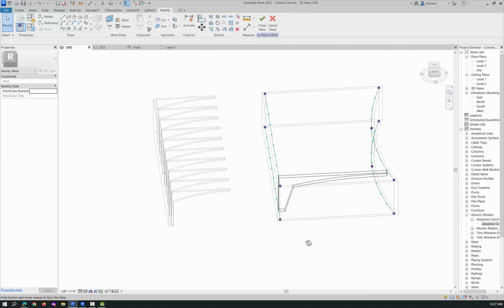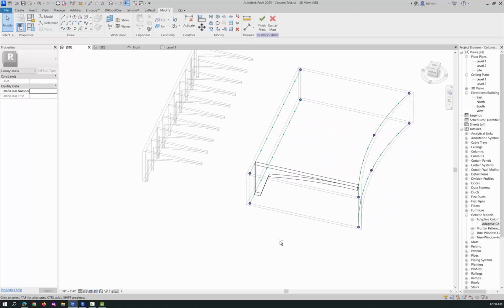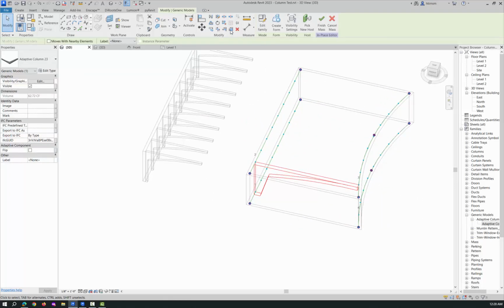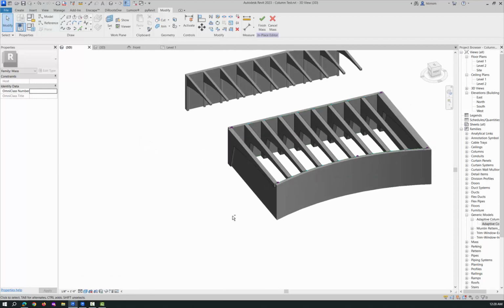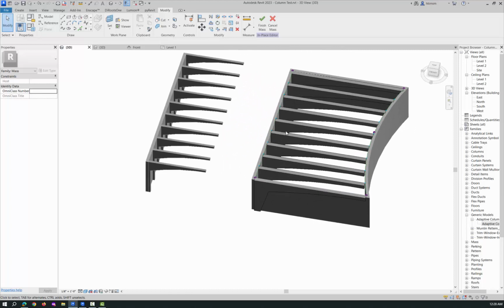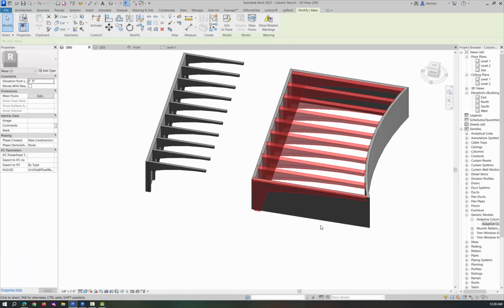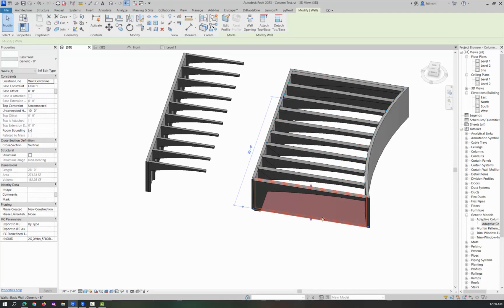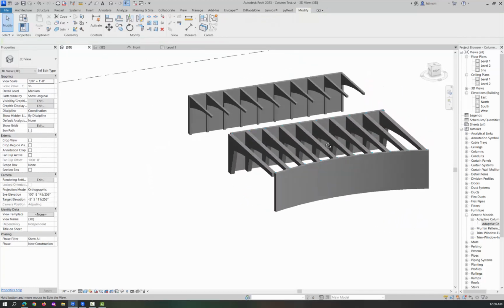And what it's going to do is it's going to follow that point. So if I pick this and I go to the repeat, it will repeat that. So let me go to shaded. Repeat that along, and I'll delete this wall. Oh, it'll repeat it, right? So if I finish the mass, right, that whole thing selects as one. Let me just delete these end walls for right now, just so we can see it a little better. You don't need the walls, all you need are the lines, right?